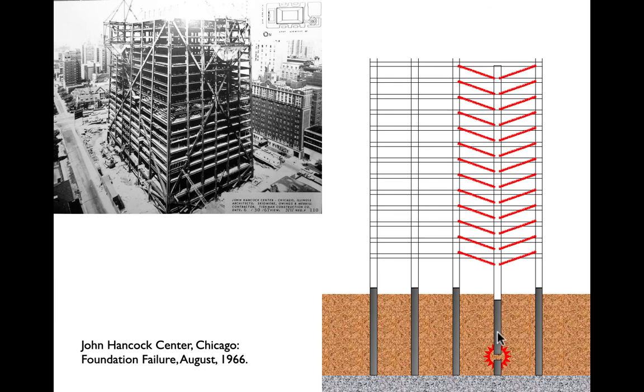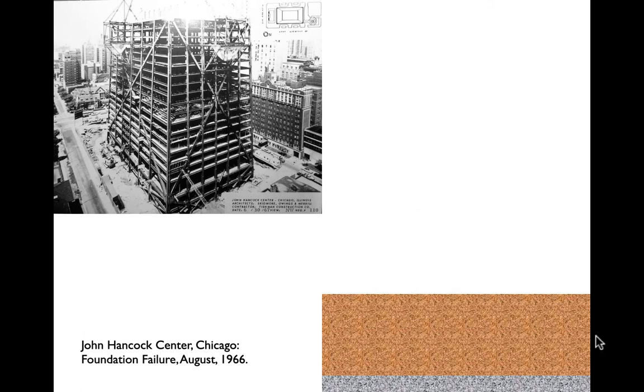In the broken caisson, what they discovered was that the caisson had somehow split, and liquid soil had rushed in to fill the void, and the caisson had collapsed. And going back into the job site communication, they figured out what had happened. The contractor had wanted to save money by reusing the caisson forms, by taking the tubes out after the caissons had cured. So remember, we're drilling down, we're making a void in the soil. There is a steel tube that's keeping the soil out.